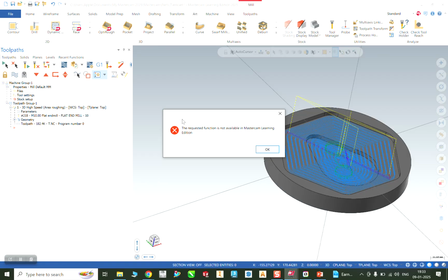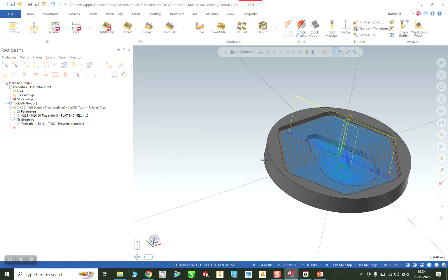It will ask on which machine you want to work. So we are going to do a 3 axis milling machine, and after that it will give you the option of what your operating system is, that is Fanuc, Siemens, or whatever type of operating system your machine has. What type of G codes and M codes it is going to accept. You need to select that and just generate, then save as, and in a Word file it is going to save that complete program.